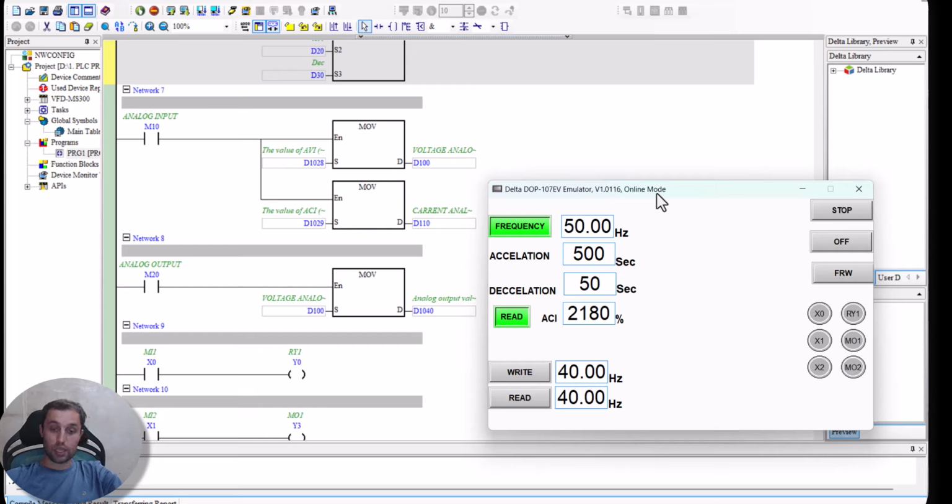So I need to check the tank, whether it is empty or not. So I also have some logic inside of this one. I wanted to buy one PLC, but actually I don't need a PLC because I don't have too many inputs and outputs. I have just 3 or 4 input outputs and only one pressure sensor, an analog input sensor. So for this one, this is the best thing. So you can use your VFD as both VFD and PLC.